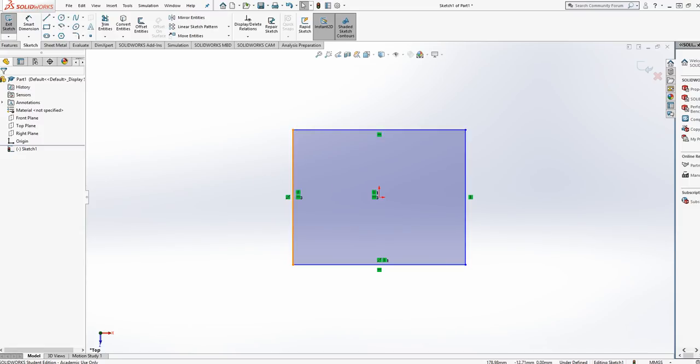Now the first thing I'm going to do is use A and B dimensions, and I know they're going to change. Okay, so I'm going to create linked dimensions with those, and I'm going to label them appropriately. Alright, so I'm going to show you how to start that. First thing I want to do is go over here to my hide show items, and I want to make sure that view dimension names is selected.